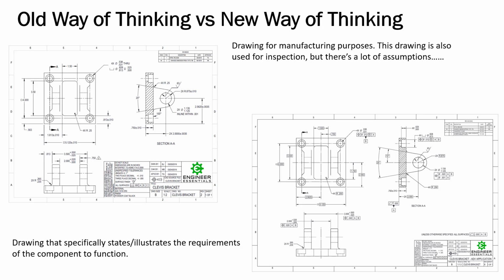And if you look at this drawing here, hopefully it's not hard to see, but just looking at the two bores here, the original drawing had on here in line within 1/1000th. And this is in inches, so it's in line within 1/1000th of an inch.